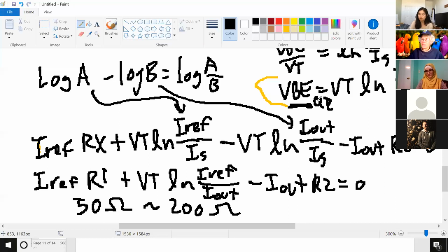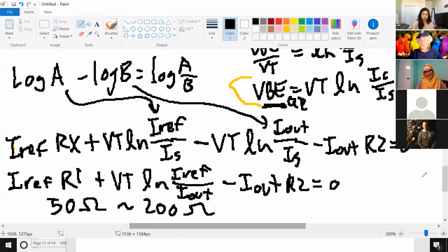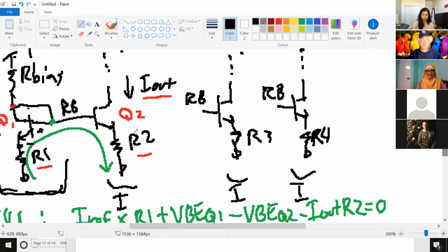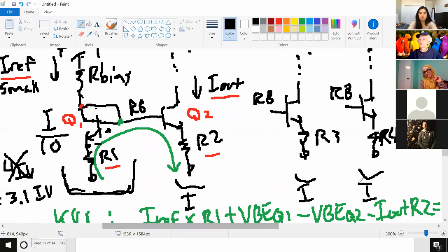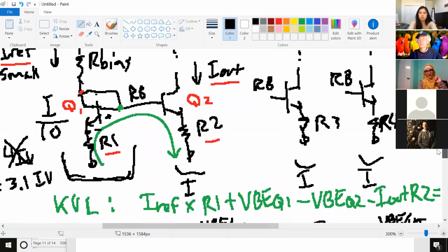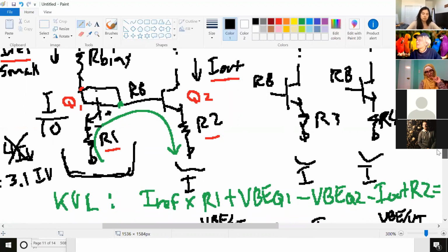Doesn't really matter. Yeah, just remember that the right side of this circuit is going to be your amplifier, and the bigger R2 is, the smaller your gain is going to be. Okay. But again, the bigger the resistance, the more protection you have against runaway currents. So we only have to worry about that. Like it's within that range that we can approximate it, but if you wanted above a certain gain, then you'd have to take that into consideration when you're doing calculations, basically. Exactly, well said. Okay, thank you.